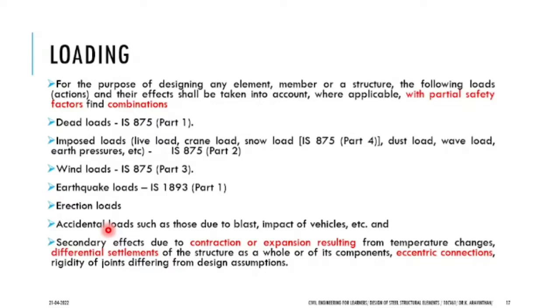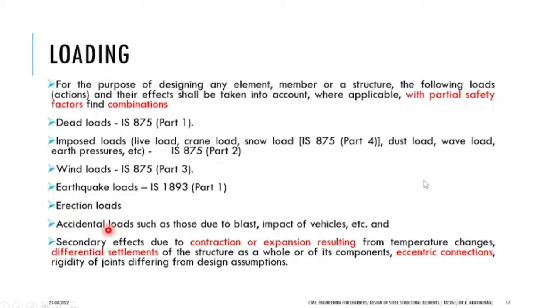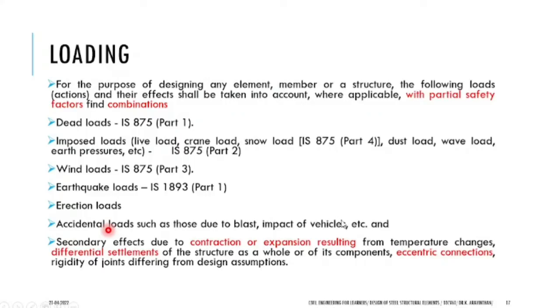So steel and concrete are bound together, yes or no? If you are vibrating a single member, both concrete and steel will get vibrated and there might be certain effects of cracking also. So that accidental load, which discusses these issues, might be blast load, impact due to vehicles, etc. Okay. There are other loads which have to be considered, which are the secondary effects.